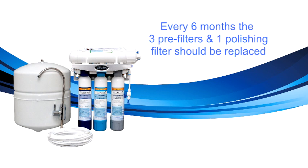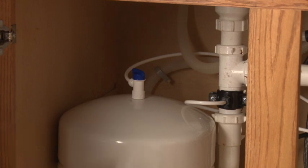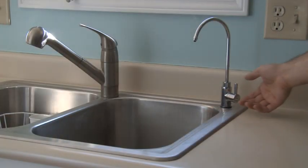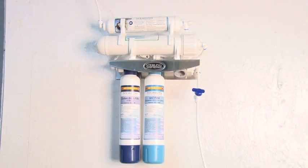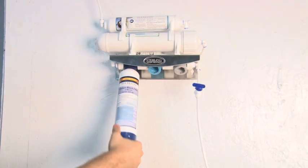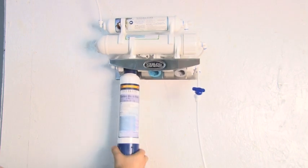Every 6 months, the 3 pre-filters and 1 polishing filter should be replaced. First, shut off the inlet valve on the system. Then close the ball valve on the storage tank and open the faucet momentarily to relieve pressure on the system. The 3 pre-filters can hinge outward and are removed with a 1/4 turn. All 3 are color-coded to the manifold. Replace all 3 maintaining their correct order.